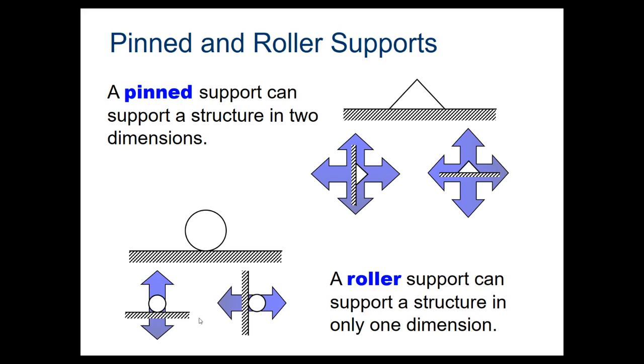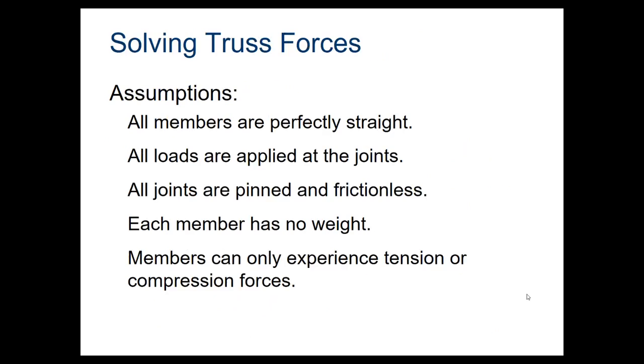For us, it's going to be this case over here, the one on the left, where we are supporting the bridge vertically. So we are going to have a support force. When we draw our bridge free body diagram, we'll have a support force vertically, but the roller joint will not have a horizontal one because it's allowing it to move that way.